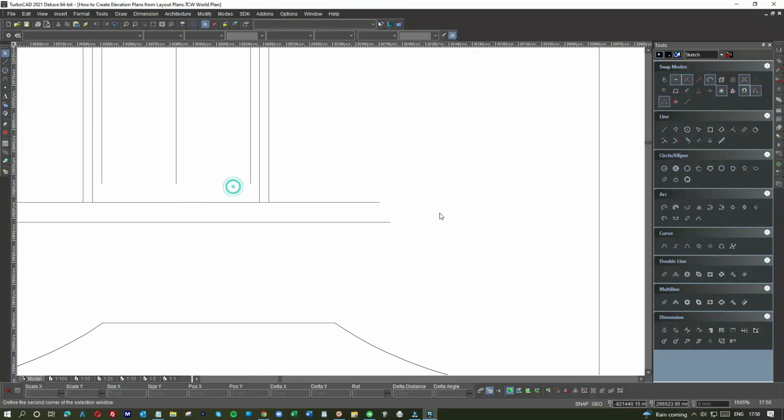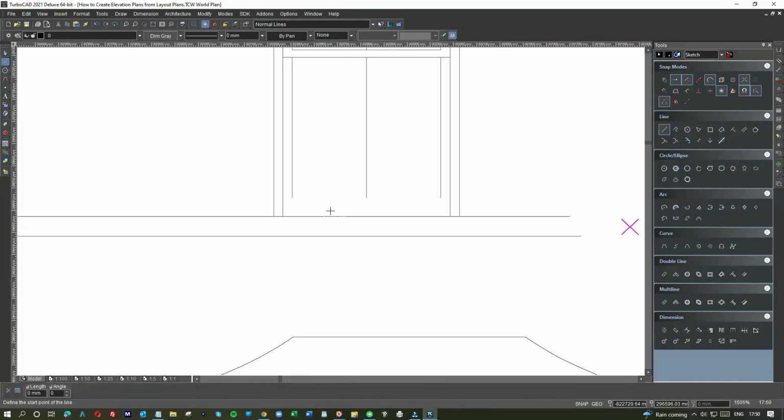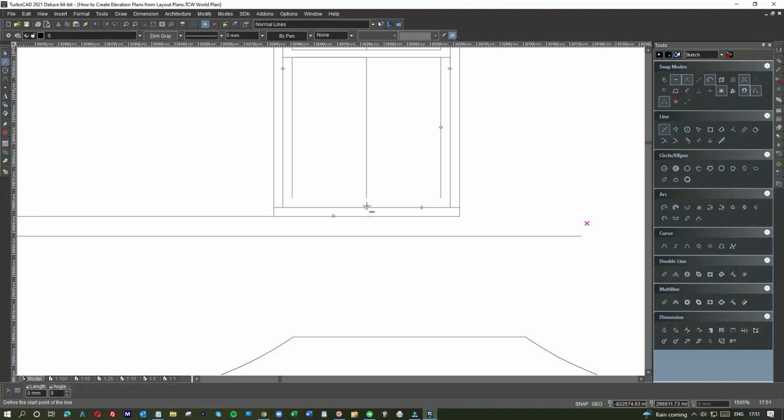What was that little piece there? Right, so that was the sill, so we need to go up, do it by hand this time, go up 40 to create a wooden sill that sits on top of the stone sill, and the box actually cuts into that, like so. Not that one, this one. Here we go, and then we need to go up 100 here.